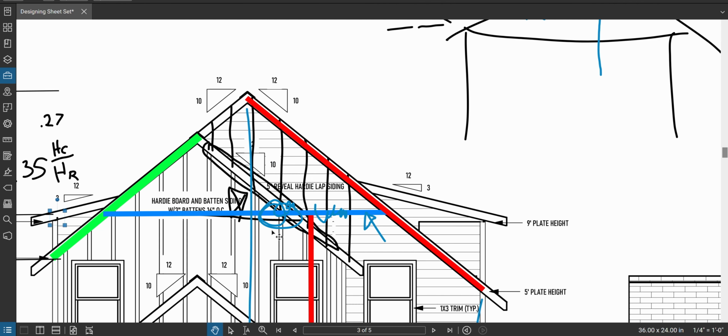All right, so I'll go to my beams. I'm going to just copy here. This is primary bedroom, right, left, front, and spans and supports. I'm going to go check the span. Right here. Oh, there's a hanger on the left side, wall on the right side. Just good to note. 5'5", we'll call it 5.5.